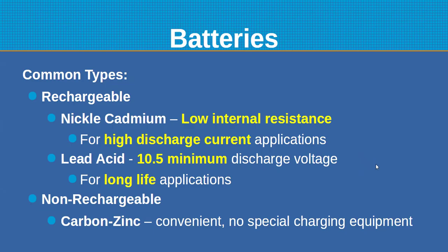Most people think a typical car battery or lead acid battery is a 12-volt battery. A nominal charge for the lead acid battery is 13.8 volts. So if you ever looked at amateur radio transceivers, they're all designed to operate off of 13.8 volts for that very reason. A charged up lead acid battery is going to be about 13.8 volts, could be a little bit higher, but that voltage will drop very rapidly to 13.8.